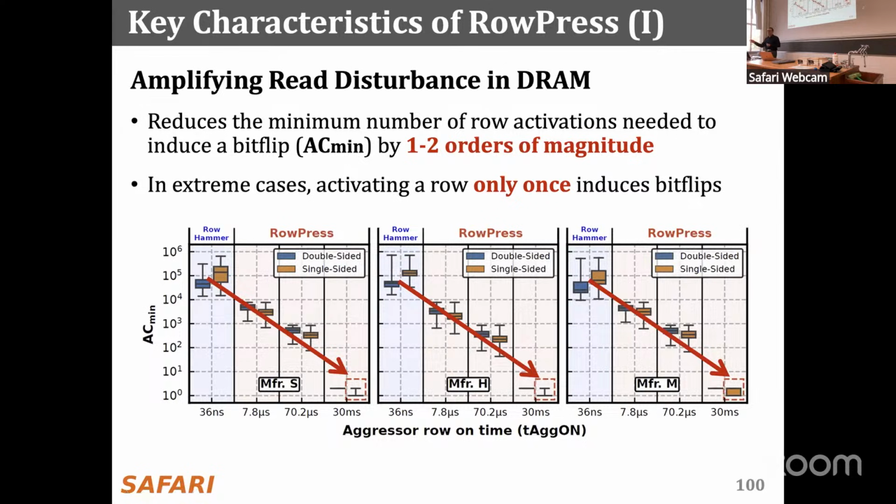And there's a mechanism called refresh scheduling in DRAM, and that gives you some elasticity in when you can schedule the refreshes. If you do that, it allows you to actually keep the row open for around 70.2 microseconds. And you can see that there's almost an order of magnitude reduction, right? So basically, that's the standard. You can do this within the standards.